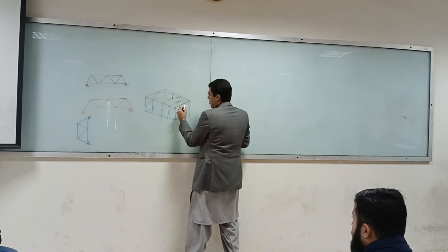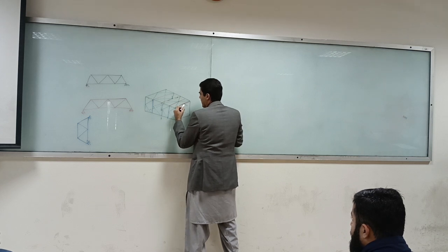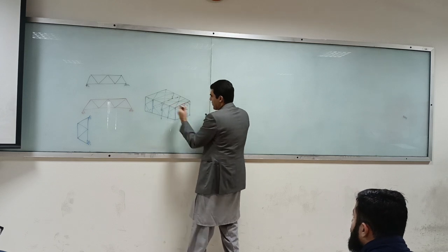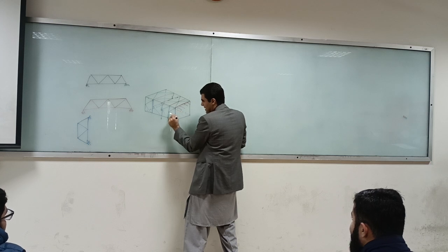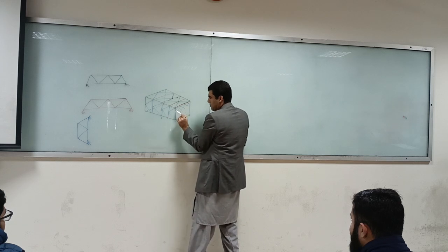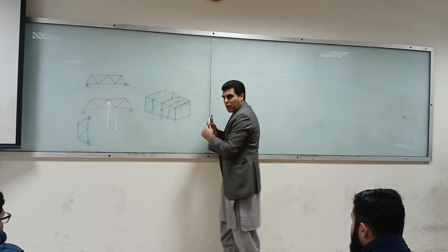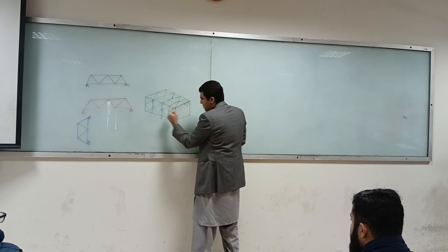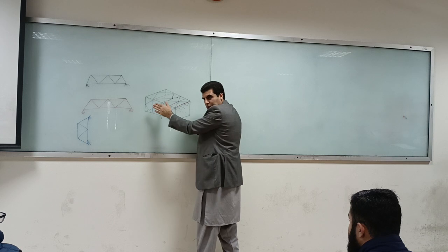So if I have a vertical load in this direction, what can happen is this load can go there, and then nicely through this truss action it can come to the ground. Do you see my point? If I had not provided these two members, this would have fallen off. But because of this truss action, this load can now go into there, and similarly you have got this black horizontal member also, which is taking the load.